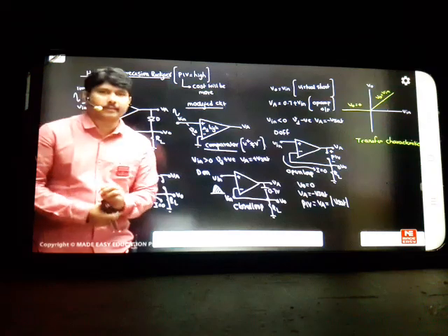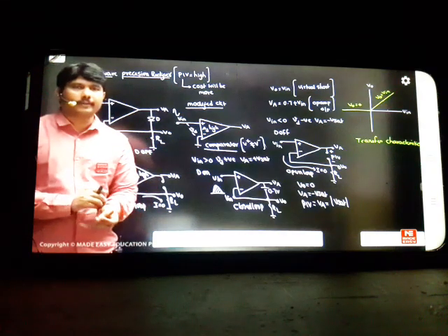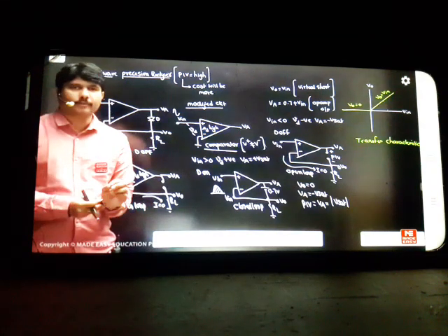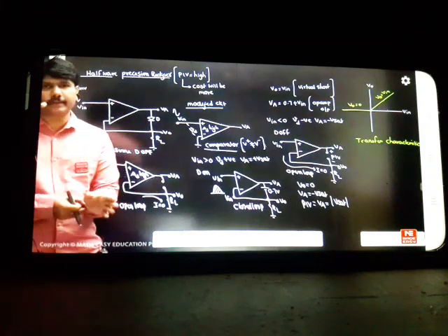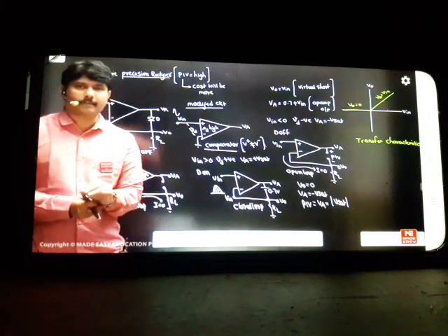In op-amps, anything you can take, okay? Inverting will accept, non-inverting, there is no worries for that. The only thing is whether you are applying positive feedback, or open loop, or a negative feedback; that will distinguish the application in electronics. It is not that if I use inverting, my application will change, or if I use non-inverting, my application will change. That is not the meaning.